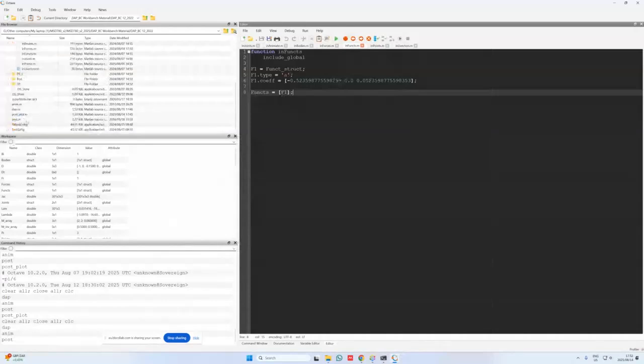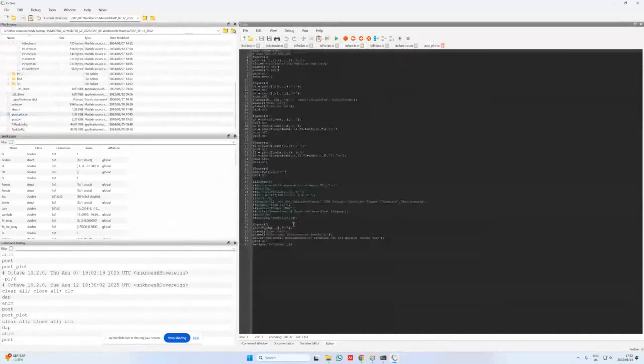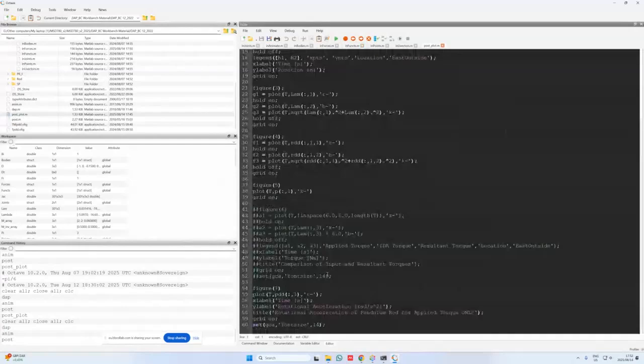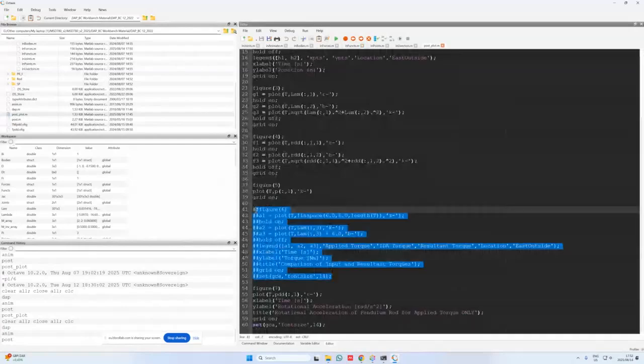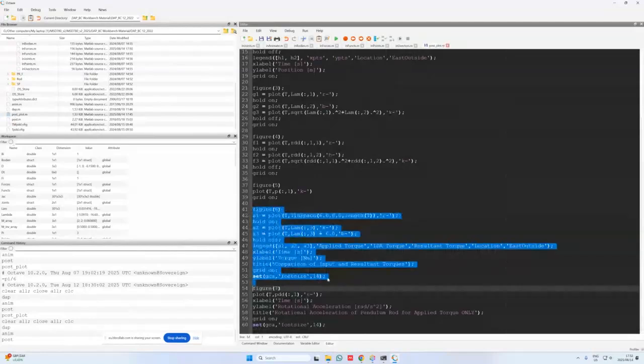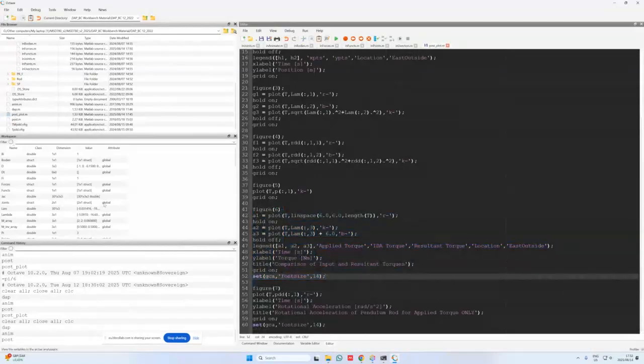And in this case, I want to go to postplot.m as well. And now I can switch on the figure 6 in this case. So I'm just going to hit Control-Shift-R, and then I can plot the third Lagrange multiplier. I know that I do have 3 Lagrange multipliers. Firstly, from the workspace, I can see that for the variable lam, it's a 301 by 3, so the number of time steps by the number of constraints that I specify on the system. And in accordance with the order in which I specified my joints as well.